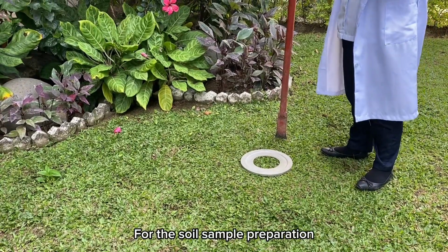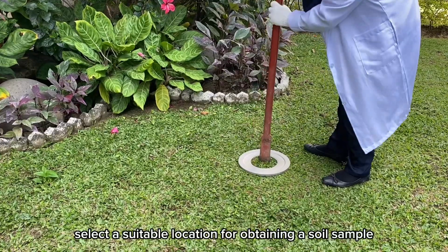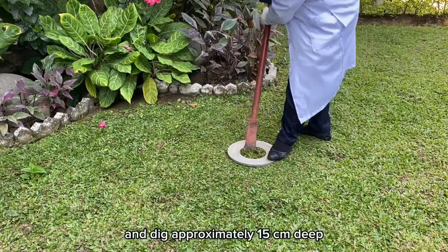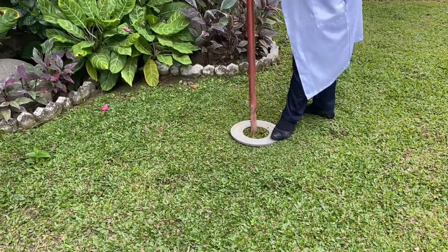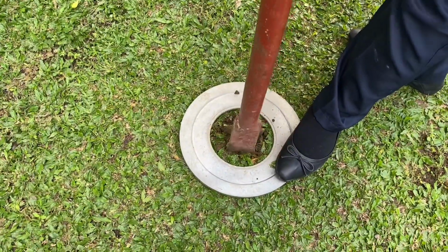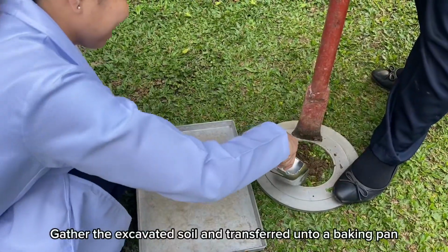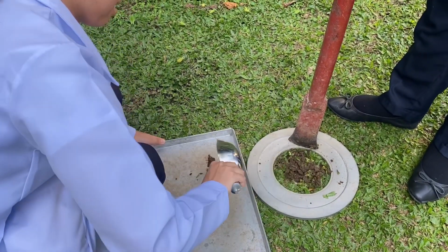For the soil sample preparation, select a suitable location for obtaining a soil sample. Place the base plate securely on top of the soil surface and dig approximately 15 cm deep. Gather the excavated soil and transfer it onto a baking pan.